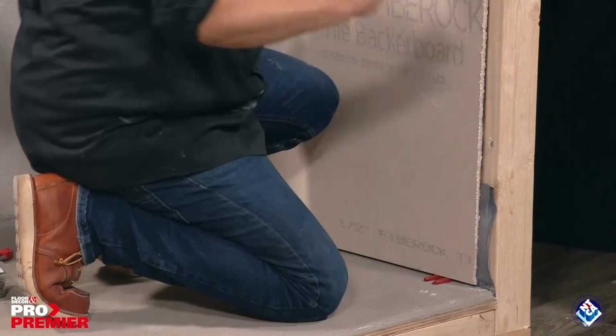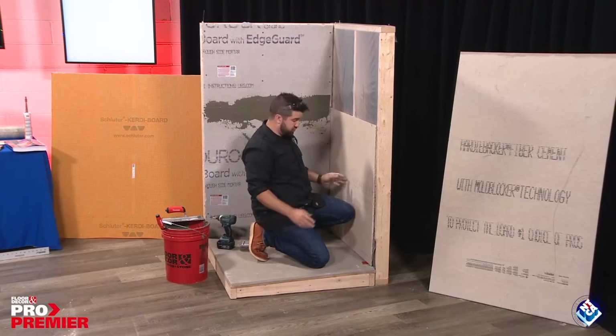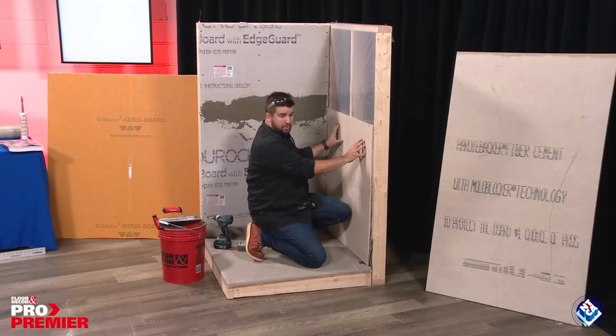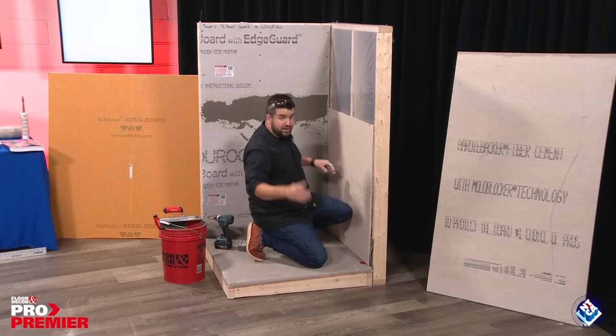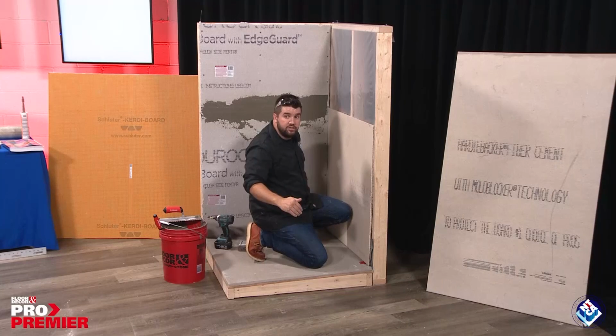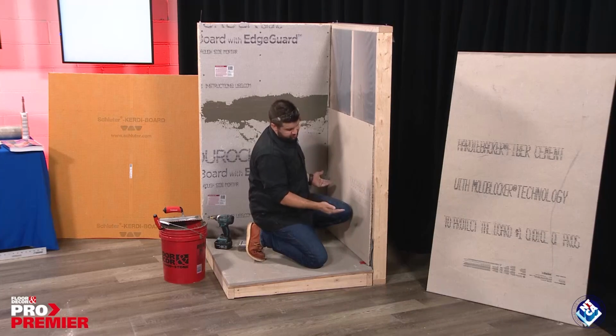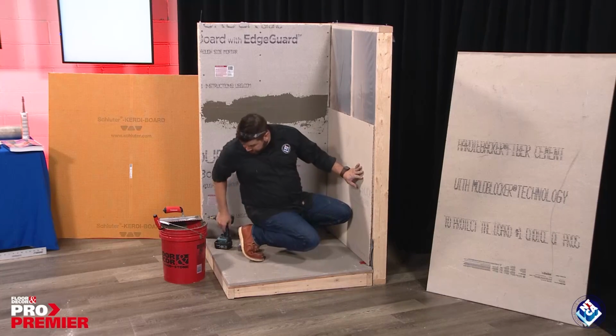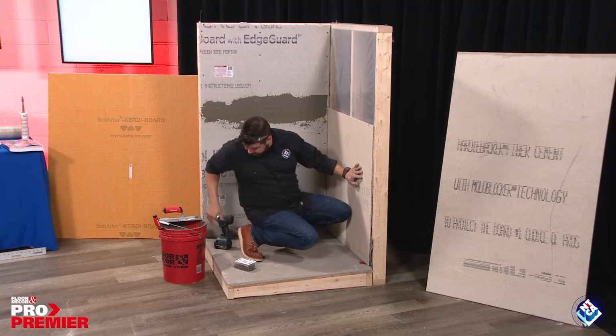So that's really the biggest difference, and you'll notice that on the screen. We want shims on the fiber rock, and on the Durarock, or on the cement board, it can get buried into the mud. The fiber board has to be shimmed up above it. So let's get some screws in here to hold this.